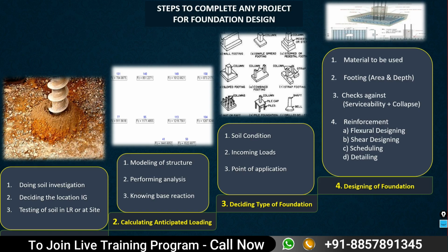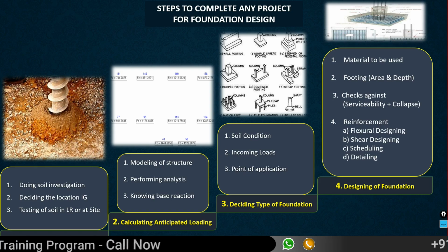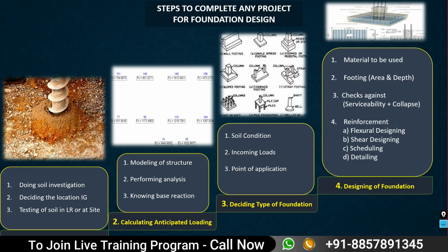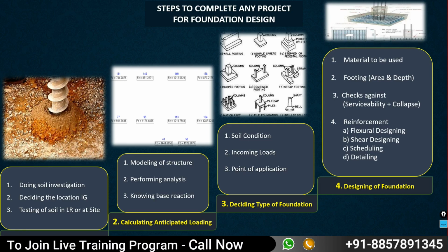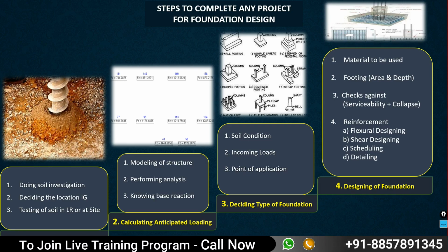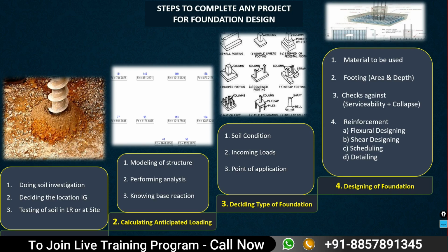We have to deal with the software, like what materials we have to use, what footing area we have to use, and what depth we need to have. Then serviceability checks will be there, in settlement and in upward soil pressure. So many things will be there. Once your analysis is right and all the checks are okay, then you go for the design of the reinforcement, flexural design, shear design, scheduling and detailing. Everything we need to do.